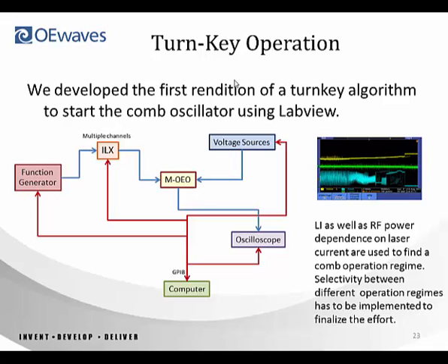We did it using a simple LabVIEW technique right now, and I would say it works pretty robustly. We don't need anybody to start it. We switch on the device, and the system, by feedback to the laser and by measuring the DC signal or LI curve and radio frequency signal power, can make it work, and it works for instance for a day. But this system has a disadvantage. We still need to find the most optimum position to generate high spectral purity signals. This is the next stage of what we're working on.